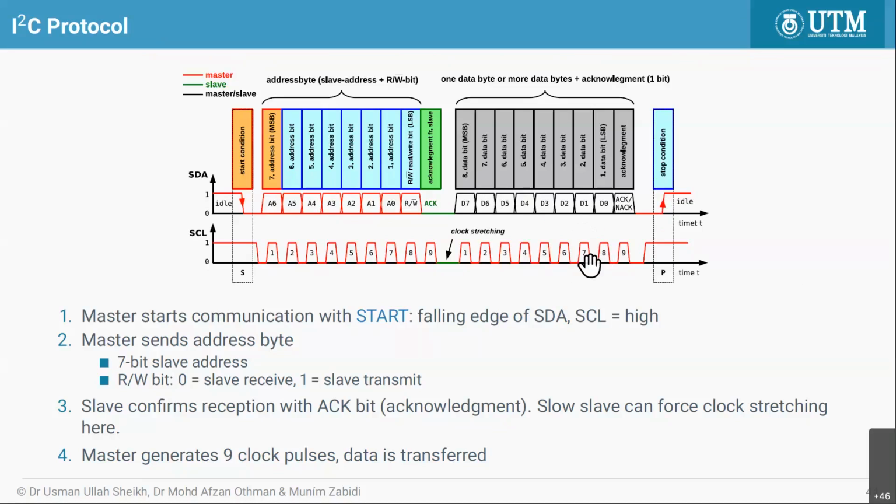So that's safe. It's no problem. It's not like an AND gate or typical TTL gate. You cannot have two or more devices driving the same wire at the same time. Open collector, no problem.